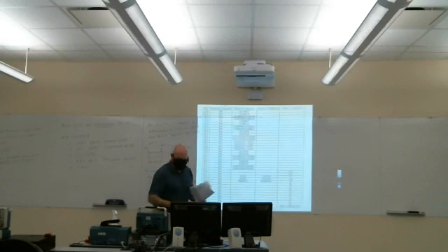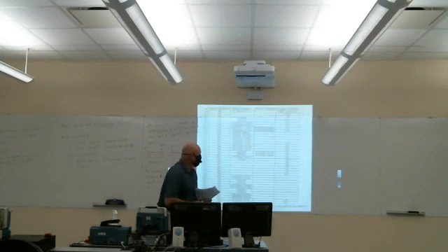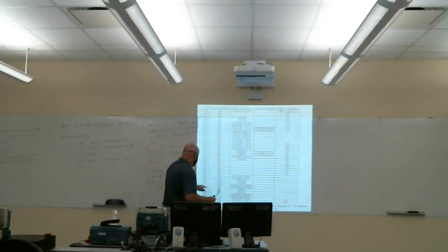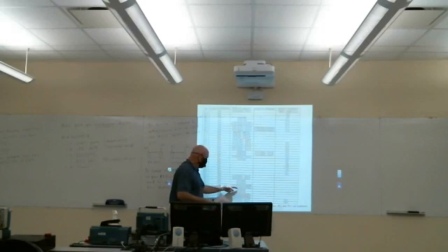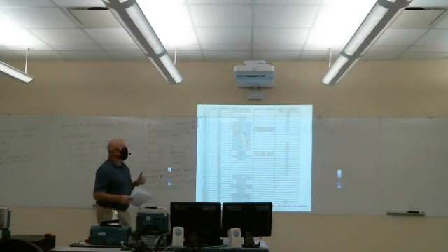Okay, so that's actually, I think, on the next slide. Let's see, port 9, 6. You see, that's for one of the other UARTs. We want to set these 6 and 7 up for their serial interface function. So that means we want to set the corresponding bits in the selection 1 register for that port to 0 and the selection 0 register to 1.